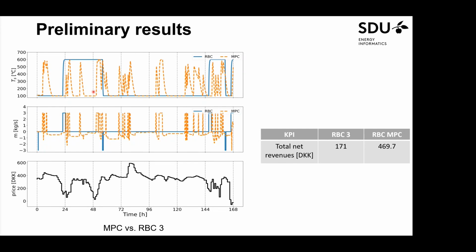see that in our control setup, we assume that charging and discharging cannot operate at the same time. So you can either charge or discharge at once. This shows how, with MPC, the mass rate of charging and discharging can vary within the range, but for the rule-based controller you can either charge or discharge with the maximum mass rate.